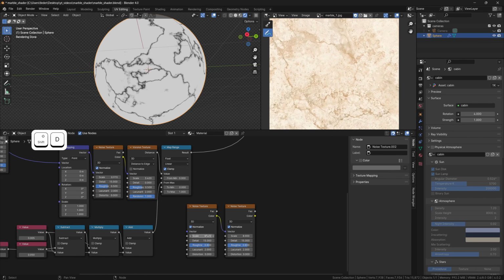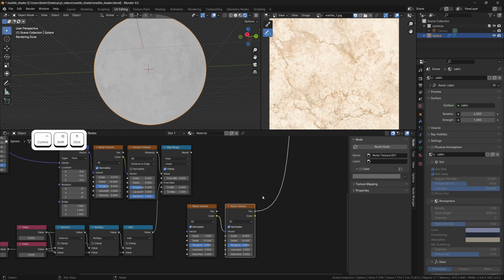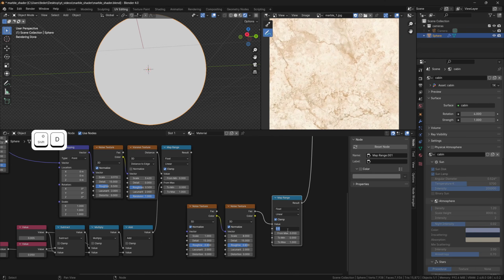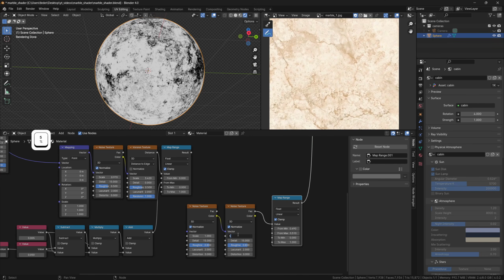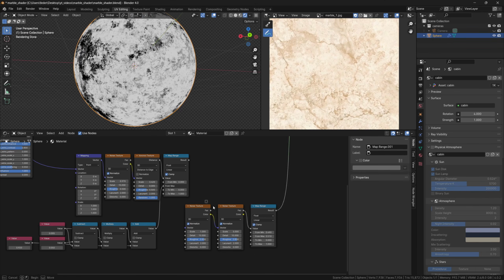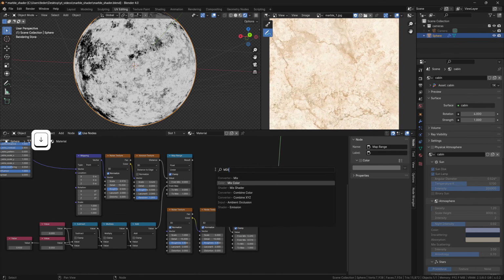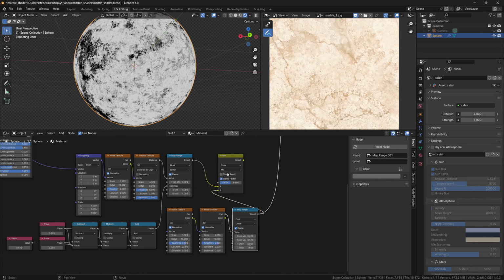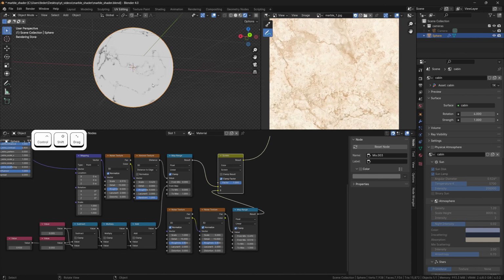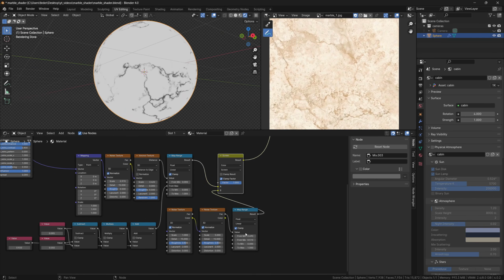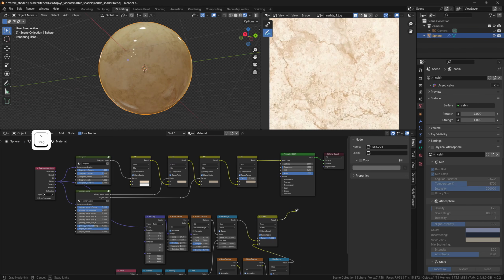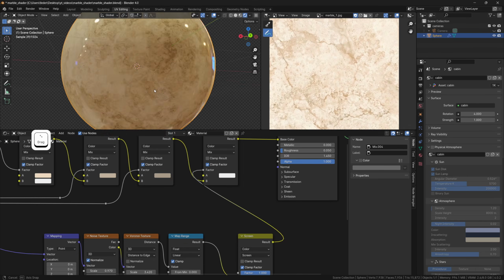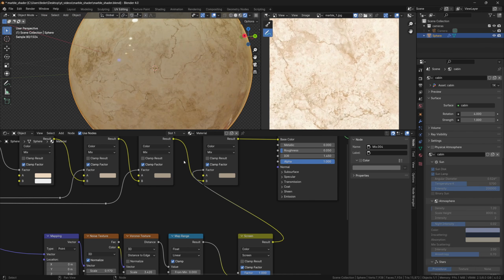What's interesting here though is the concept that apart from building patterns, it is also very important to learn how to break them. With the double noise texture combo we already used a few times, I'll create another black and white mask to be then mixed with the output of the Voronoi, and the aim here is to break the uniformity of the latter and to try to achieve a more disconnected kind of look for the lines that are representing the veins. I'll then test the mask through an additional mixed color node, playing around with the parameters as well as with different potential color tones.